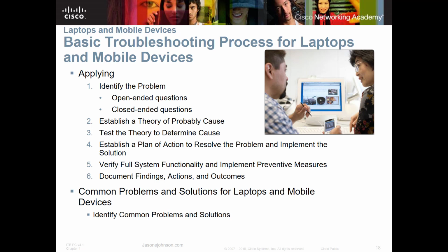The same thing here, we apply, we identify the problem, and I'm going to move through these really rapidly because we've covered these in previous chapters. You identify the problem, you ask open-ended questions and closed-ended questions to find out when was the last time it booted. You try to find out, well, every time I unplug it, the laptop dies. Well, that lets you know that it may be a battery issue. I spilled soda on it, it just stopped working. Well, that's a pretty good indication of what happened.